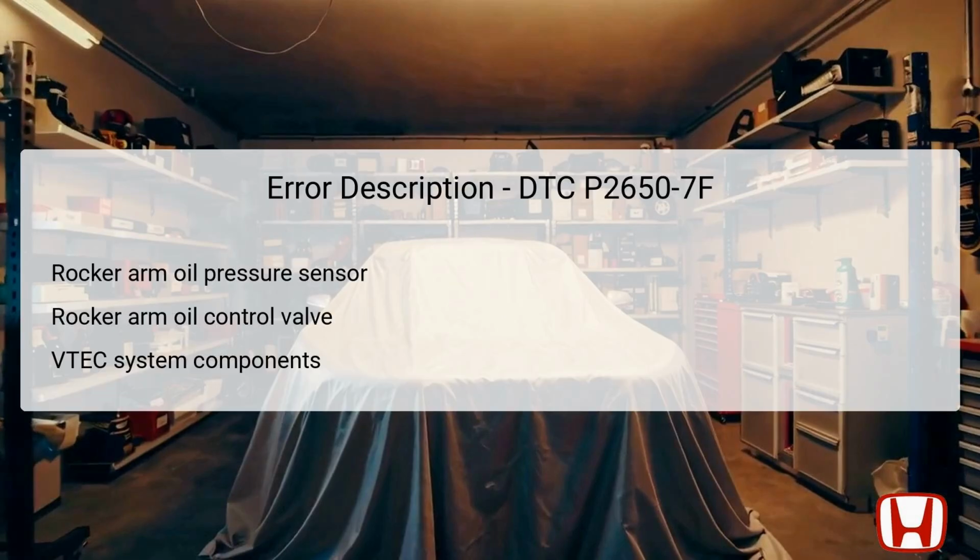The error code DTC P2650-7F indicates that the rocker arm oil pressure sensor output remains low when the rocker arm oil control solenoid is activated. This abnormal indication suggests a malfunction within the rocker arm oil pressure regulating system. The rocker arm oil pressure sensor plays a vital role by delivering real-time oil pressure data to the powertrain control module, PCM, to manage the rocker arm operation effectively.